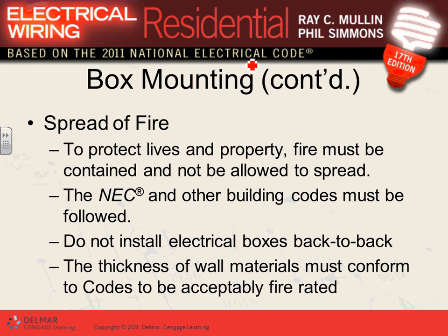Spread of fire. This little bit talks about the spread of fire and why we put them all in the boxes. Building code. The other building codes, guys, also require you to do what the NEC is doing. Do not install electrical boxes back to back.